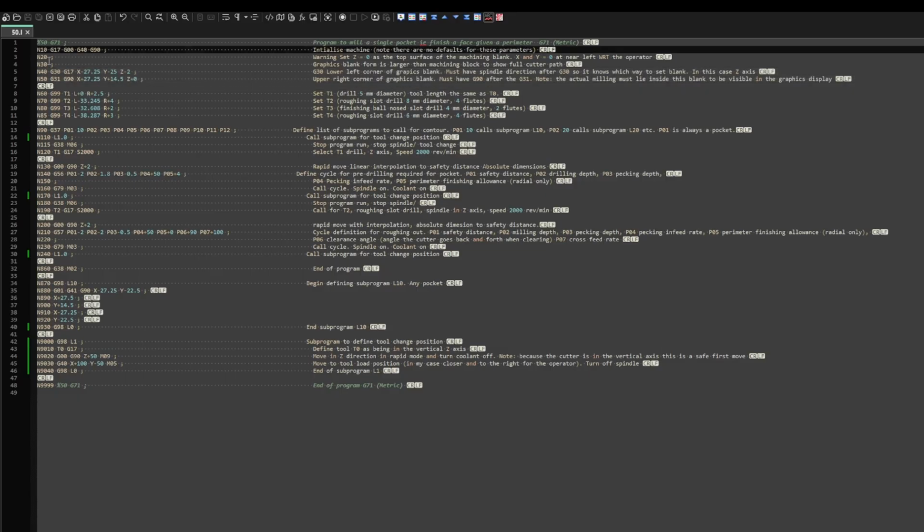This up here is to do with the Heidenhain being able to be put on multiple different types of machine, and so they don't have defaults for a lot of the initial values, and there's 4 groups of them, and you pick one out of each of those groups. So this is telling you that the tool's going to be in the Z spindle tool holder.